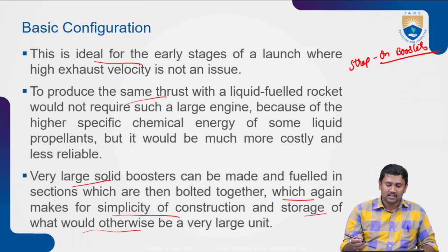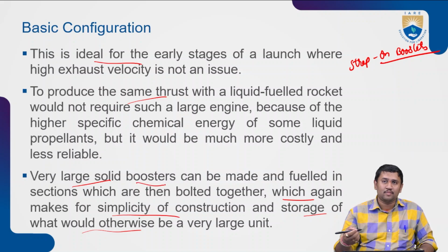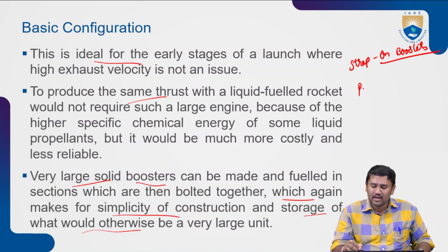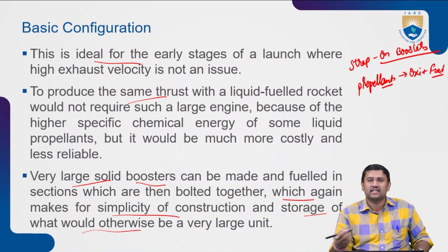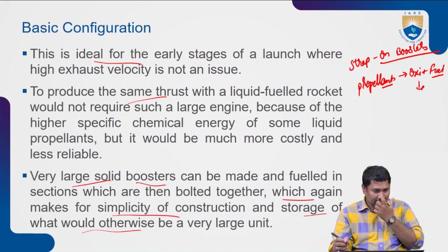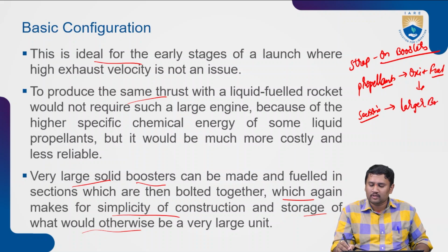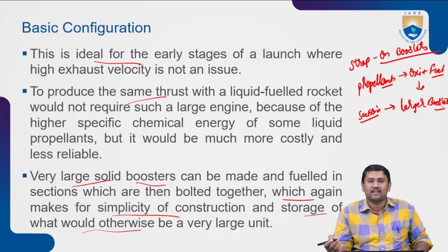Now, coming to this, very large solid boosters can be made as well as fueled in sections, right? As we know, the propellant, particularly the solid propellant, is a mixture of finely ground oxidizer plus fuel in certain proportions according to the manufacturer's discretion. Now, these can be created as sections, then added to form a larger booster as and when required, right?